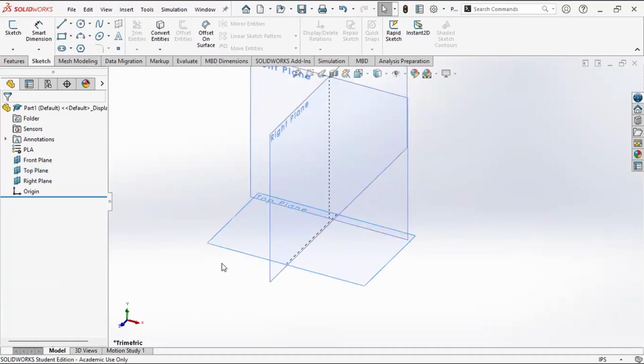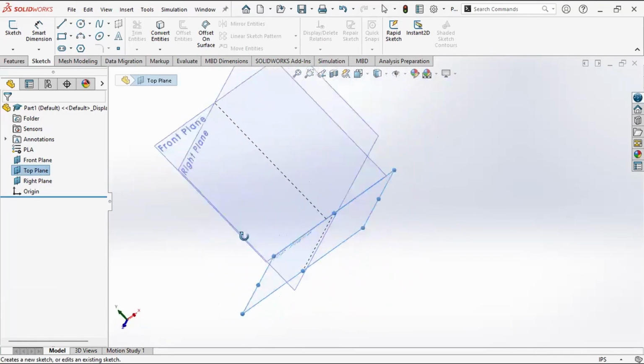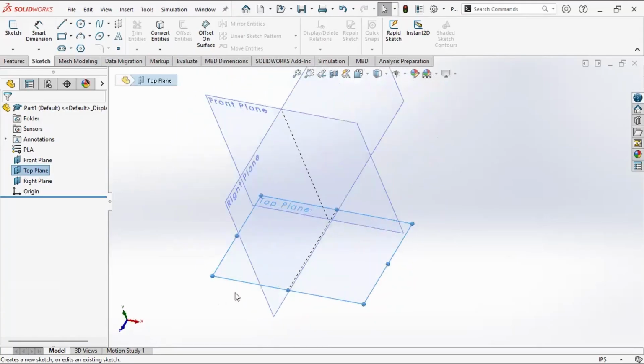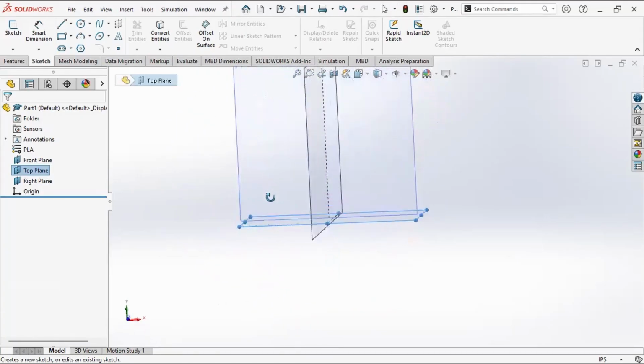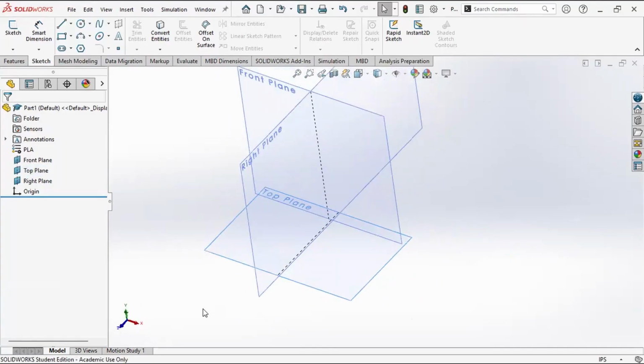Something like this. But we've got three planes, and these planes correspond to directions in three-dimensional space. If you look in the model window, that's the window where the planes show up, down here in the bottom left is an XYZ coordinate system. So if I center click on my mouse, I can rotate this. You see my XYZ rotates along with the planes. So center clicking, that's your scroll wheel, and pushing it down is how I rotate this. And that's how I can get a different view of these things.